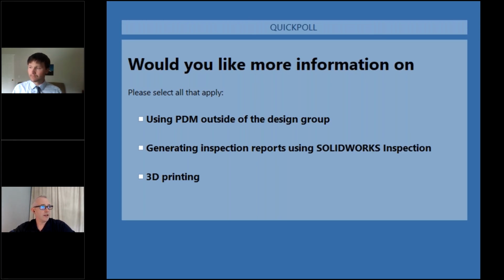Yeah, that is, I think, the more common use case. However, it really depends on what you're trying to achieve. If you're doing most of your drawings in SOLIDWORKS and you're not receiving drawings from your customers as PDFs, then it might make more sense to do that in SOLIDWORKS using the add-in. If you are manufacturing components for other companies as a job shop or something along those lines, then because you're receiving PDFs, you'd be using the standalone more often to use what's called optical character recognition on those PDF files to plug that information into your FAI report.